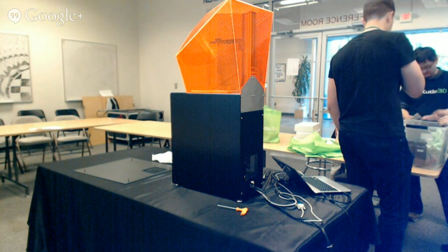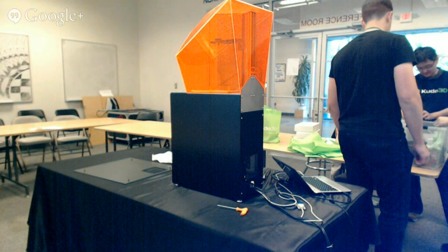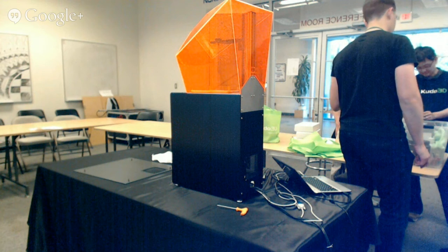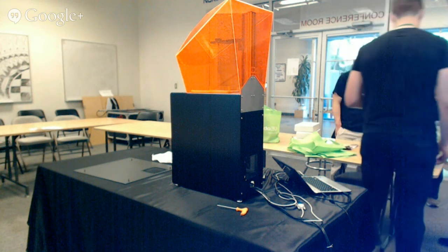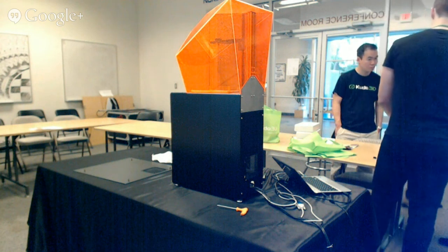A friend of mine cut that out on the lathe out of steel. Oh, the angle. So what you do is you put it in the vise and you put an angle here to angle it, and then to make this surface here. Right. Yes. And then I take a face mill and just face this off.